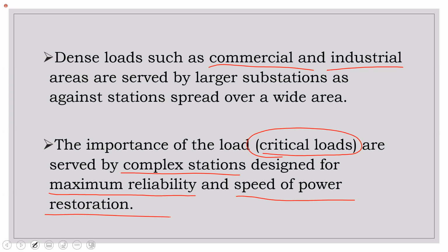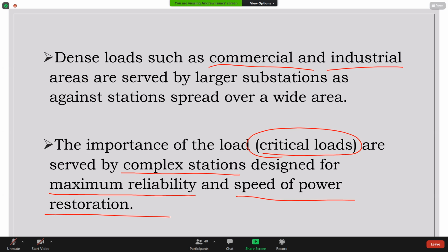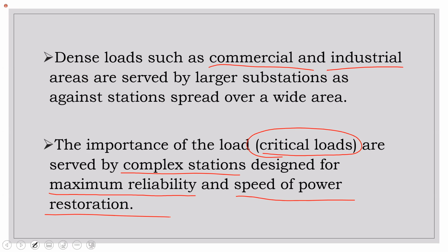What are some of the other considerations as it relates to load and voltage and space, right? We have to bear in mind that we're going to have growth in load, but growth in what type of load? So I suppose when we talk about load growth, persons are going to say, well, you know, yes, they must have had capacity there for increased load. So if a man puts up, starts to run even a tire shop where he's running his compressor, the compressor puts on reactive loads on the system because he's now running motors.